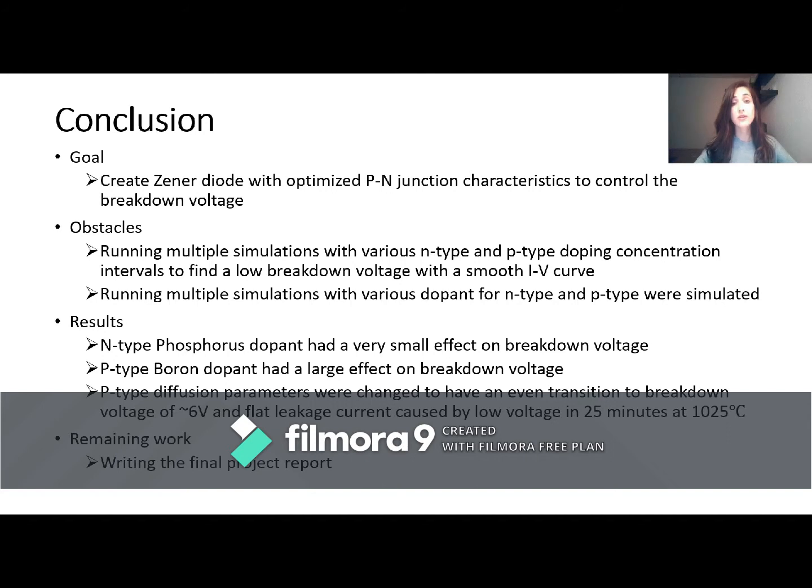In a case of large forward bias, there is some voltage drop across the diode due to its p-n junction built-in voltage and internal resistance. The amount of this voltage drop depends on the semiconductor material and the doping concentration.